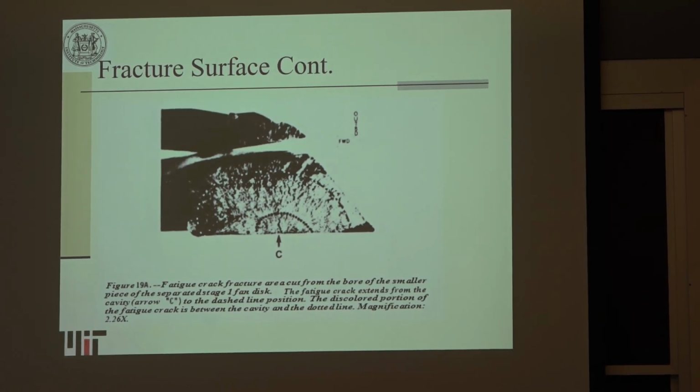With the hard alpha inclusion, what it led to was a brittle region that would have local high hardness compared to the rest. To confirm whether it was an inclusion or not, you could do micro hardness on the part, as well as look at the visual features of the thumbnail fatigue crack. You have your origin region here. Fatigue progresses to the point where you have final fracture through the remaining cross-section of the fracture surface.